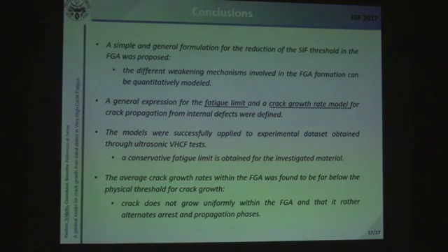To conclude very briefly, a simple general formulation for the reduction of the stress intensity factor threshold is proposed, and this model permits to model all the weakening mechanisms involved in the FGA formation. A general expression for the fatigue limit and crack growth rate model is also proposed and defined, and this model was successfully applied to an experimental data set and validated, and we obtain a very conservative fatigue limit that can be used for design purposes.